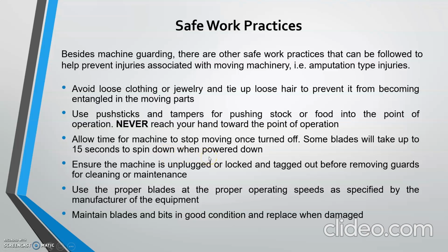It does not fully stop, right. When you push the turn off button, it does not automatically stop, so there is still a delay time. And then ensure the machine is unplugged, locked and tagged out before removing guard for cleaning or maintenance.